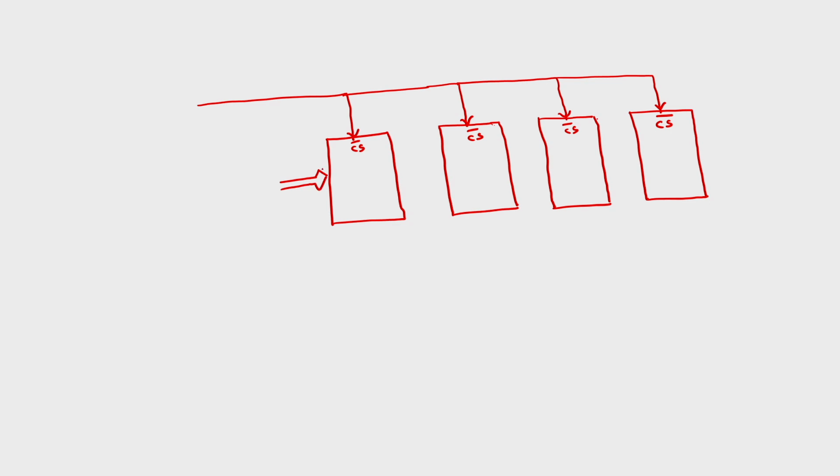Simply connect all the chip selects together. All the 4 memories will be selected simultaneously. All have the same number of address lines, 5 address lines A4 to A0.